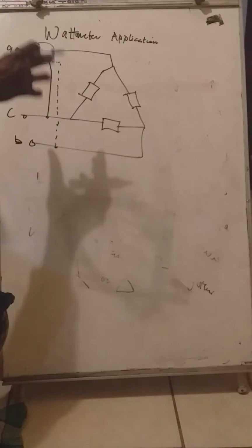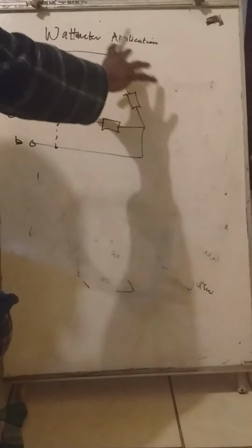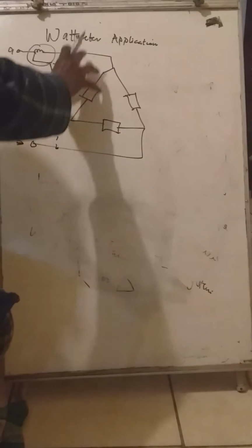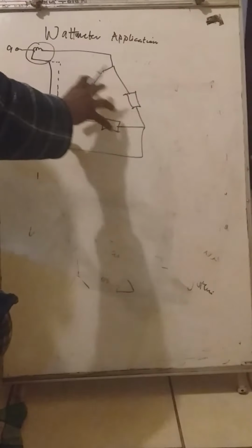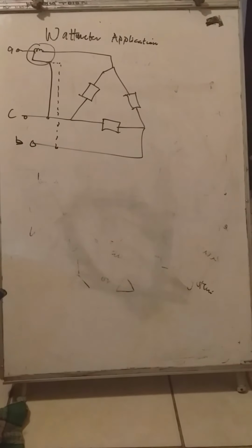The two wattmeter readings that you take, you add together, that will give you the total load consumed power, the total reading of the wattmeter on this particular circuit.